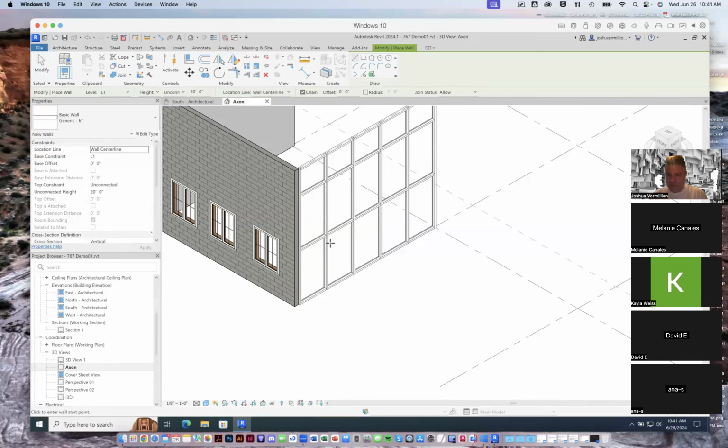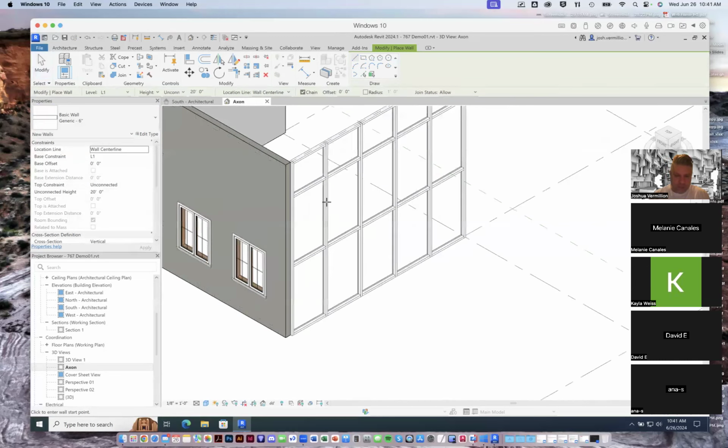You just simply put silicone between the glass, butt joint it, and then bolt everything together with some hardware, rather than sliding things into mullions. The mullions, I mean the frame, right? The frames, the vertical and horizontal members that are usually aluminum. So you'll see oftentimes a variety of glazing systems.